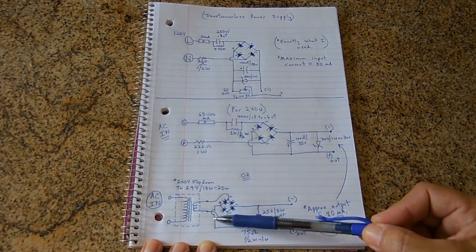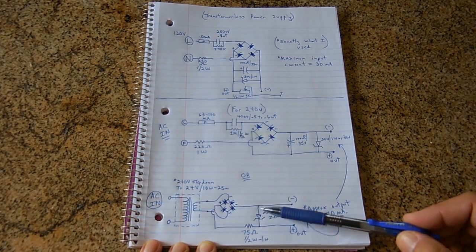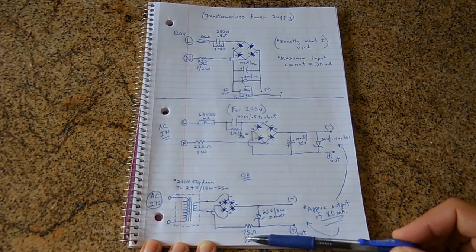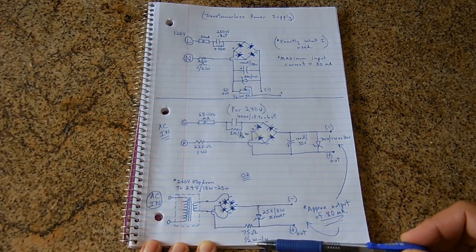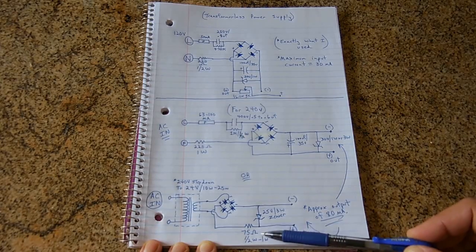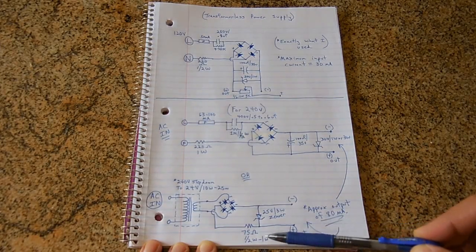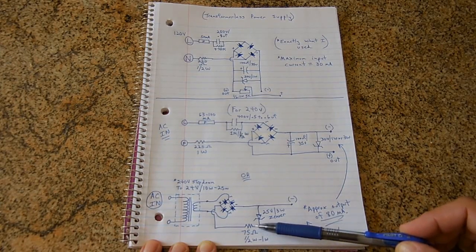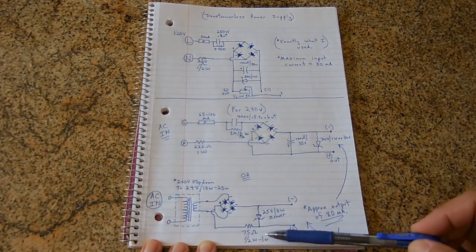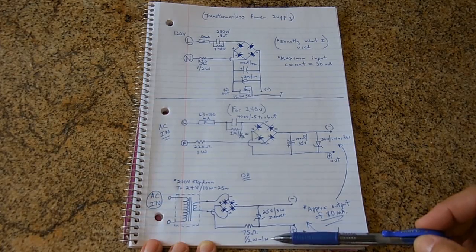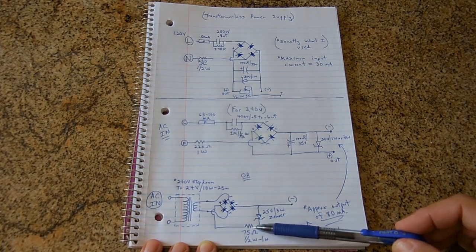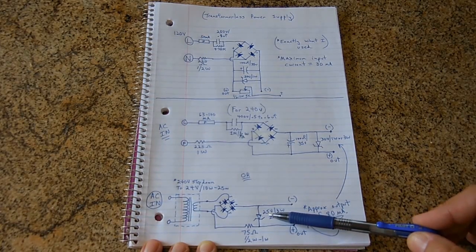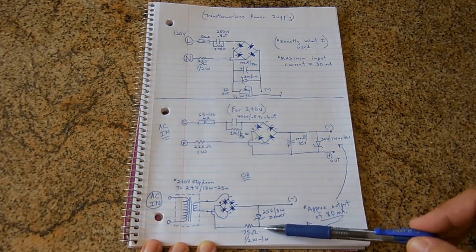The positive output comes across into this Zener regulator circuit, 75 ohm resistor, 1/2 watt to 1 watt. If you run the circuit and it works fine and you notice that this is not getting hot, then you leave it with the 1/2 watt. If you notice this is becoming too hot, you're going to want to increase the wattage to 1 watt so this runs cooler. The Zener is a 25 volt 3 watt Zener.